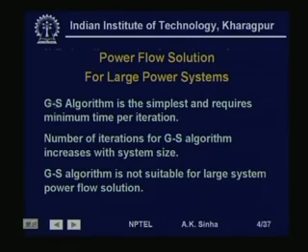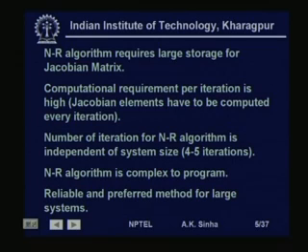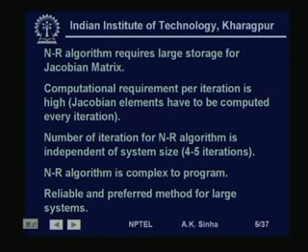In fact, the Newton-Raphson method was known earlier, but it could not be used for the power flow problem, mainly because for large systems it required solution of a large Jacobian matrix, that is, a large system of equations, which was not possible earlier. That is, the Newton-Raphson algorithm requires large storage for the Jacobian matrix.